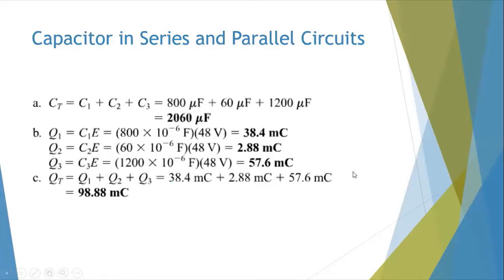So just briefly, since the capacitors now are connected in parallel, the sum of capacitances will give a total capacitance. And like we said, the formula is Q is equal to CV. Since the capacitors are all connected in parallel, they will have the same voltage across them as the battery EMF. That's why it's the same here. And then you just have to multiply the individual capacitances by the voltage across it. So you get the individual Q1, Q2, Q3. And since it is connected in parallel, the sum of the individual charges will give us the total charge, and you can answer that.